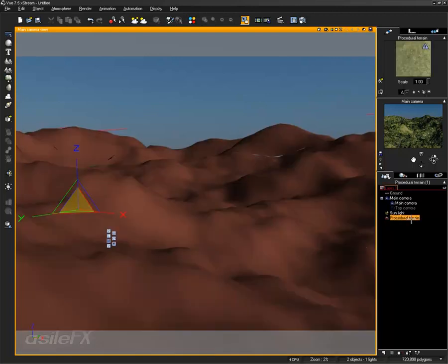Because we had created a duplicate object, what it did was transfer over the material to the new object. So we had two materials with the same name. Now, there's a huge difference between scale sizes between a standard terrain and a procedural terrain. And I think the error was probably due to that material transfer.